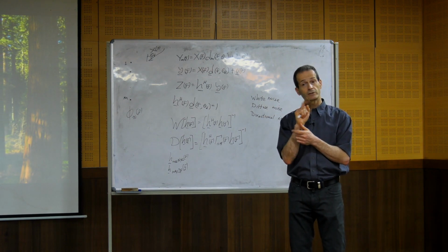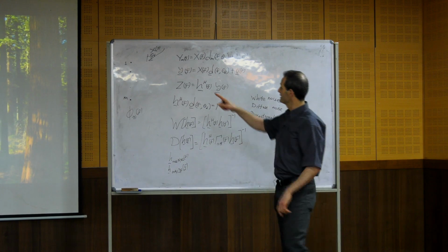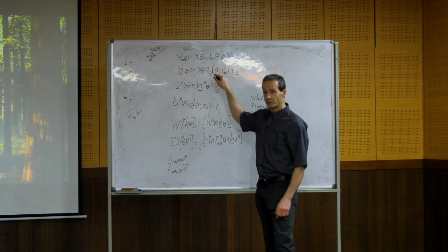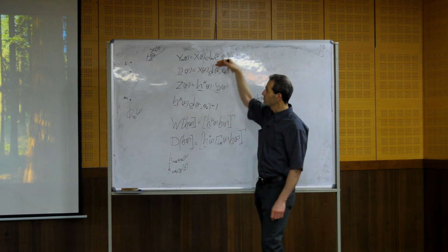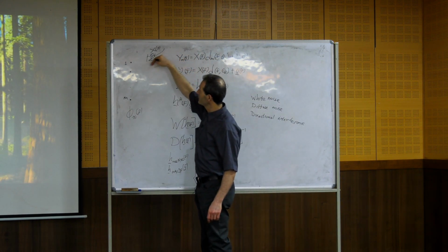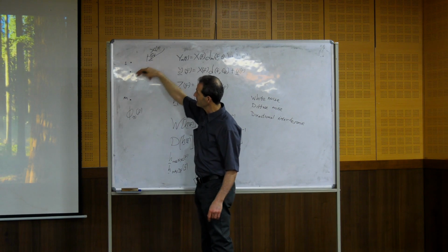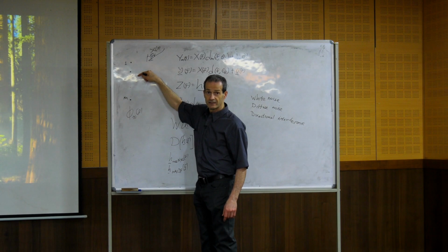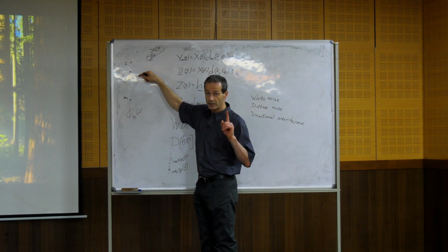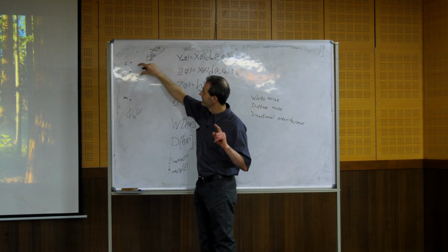And this is very important because, you see this steering vector, we assume that all sensors have the same response. So the propagating wave that hits one sensor and another sensor, the differences in phase are a result of the direction and the distance.